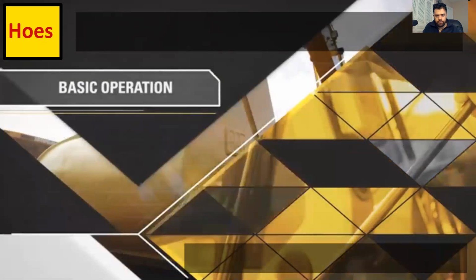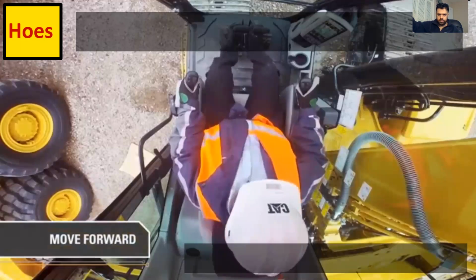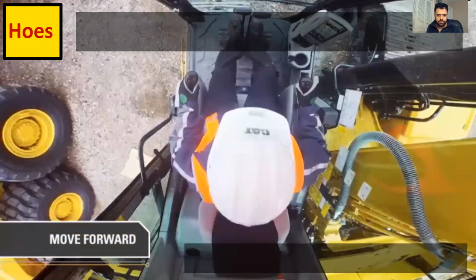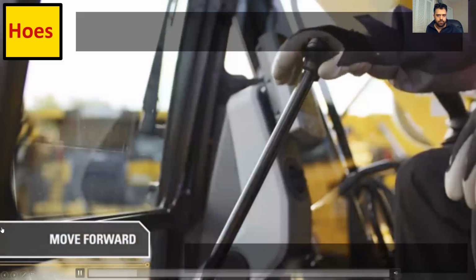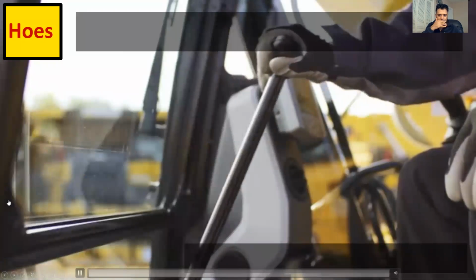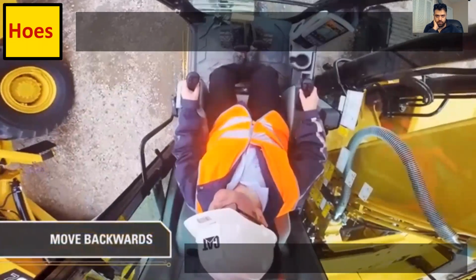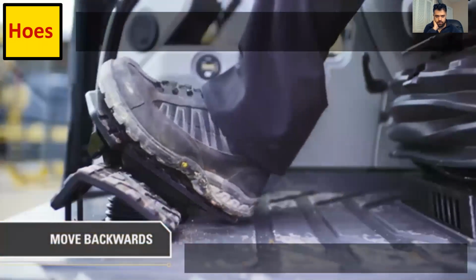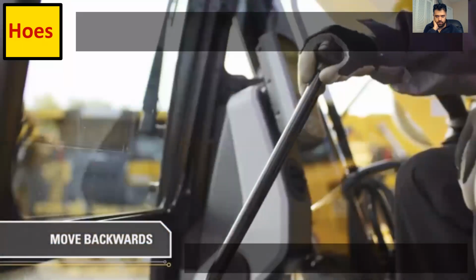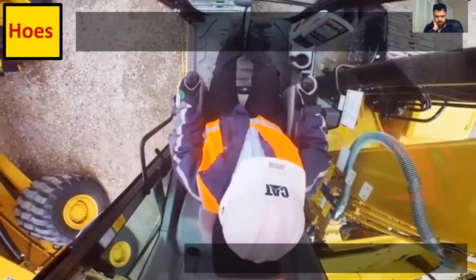Basic operation. To move your Cat excavator forward, simultaneously press the two pedals forward. Alternatively, use your hands to move the two track levers forward. Bring them back to the neutral position to cease movement. Moving backwards requires the opposite motion, either pressing with the heel on the pedals or moving the levers towards yourself with your hands. Each lever or pedal is relayed to one track.